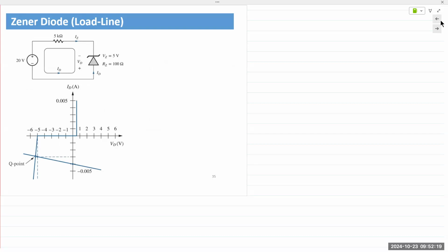Now, if you think back to the beginning of the chapter, we spoke about PN junctions and PN junctions in reverse bias specifically. In reverse bias, with increasing voltage, with increasing electric field, the depletion region keeps getting wider and wider until the diode reaches a region known as breakdown, where a whole bunch of carriers acquire enough energy to cross over the junction and current flows in the opposite direction.